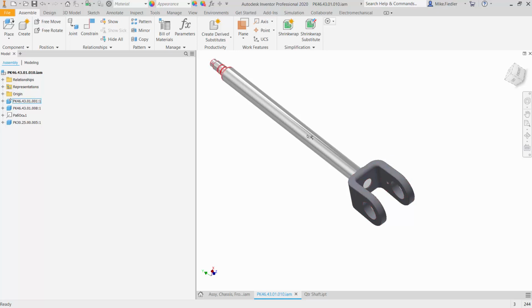So we have two ways that we could approach that, right? We could take this shaft, cool it down, and insert it into this joint and allow it to come back to ambient conditions, or we could heat up the bracket here, or joint, and then once it's expanded, move it on top of the shaft.